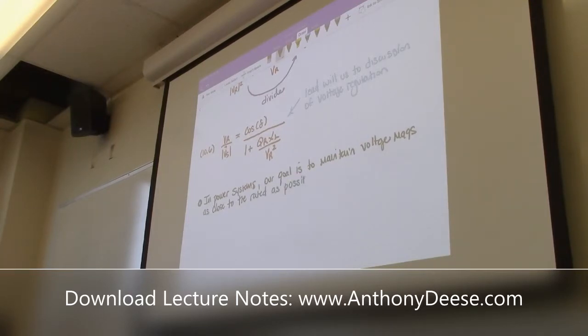Now there's a whole wide array of reasons why that's true. Number one is because obviously that's the value at which it's designed to operate. But in addition to that, we know that the region of stability for these values is relatively small. So assuming that the generators are operating at 1 per unit, which they should be, right, that's our reference point.